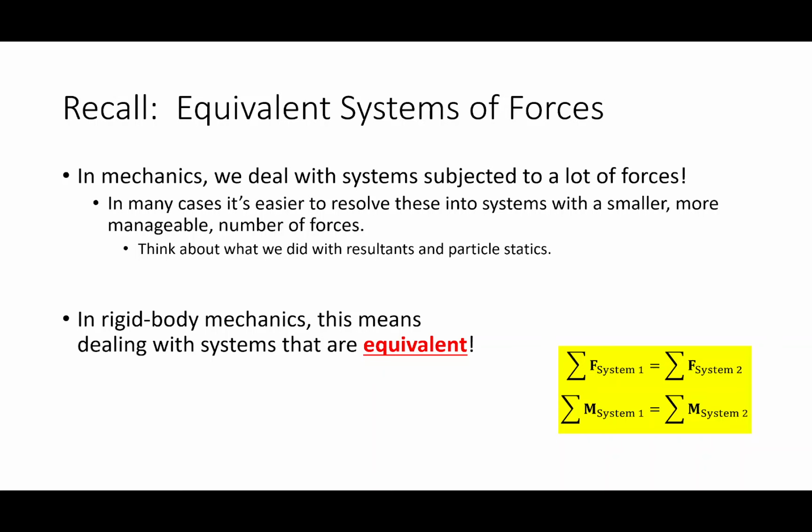And I think what's new is this notation, where for moments, it's the same idea. Add up all the moment coefficients in front of i, the moment coefficients in front of j, the moment coefficients in front of k. Make sense? Okay. So this would be a resultant force vector and a resultant moment vector. And what I've got here are really 6 independent terms in 3D: 3 force expressions, 3 moment expressions.